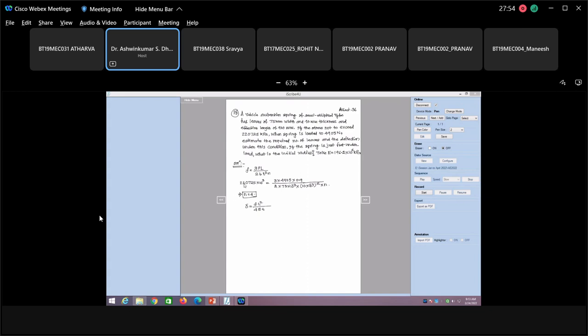Okay. So F is given as 220725 into 10 raised to power 3, since it is given in kilopascal, so the 10 raised to power 3 is there. L is given, so 0.9 squared, divided by 4 multiplied by E, 196.2 into 10 raised to power 6 into 10 raised to power 3, that is in pascal, into thickness.